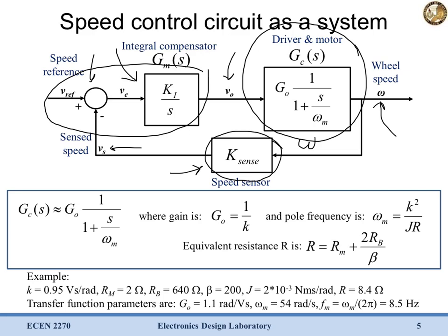Now the transfer function for that motor driver we didn't derive directly, but there are some materials online to show you how to do that. What's important to note is that we can model this motor as a single pole system. So you can see here we have some gain on this transfer function, some G0, also seen down here, where G0 is dependent on our motor parameters.